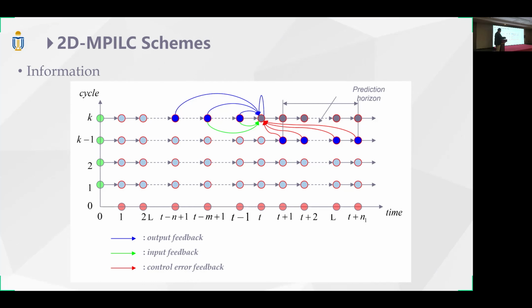One is the traditional time, and the other is batch: one batch, two batch, three batch, the k-th batch, it's repeating itself. So we describe the batch process with two time dimensions, one the traditional time t and the other the batch dimension k, as two-time dimensional dynamics. With this, it's possible for us to use information from the past. And also, the beauty of two-time dimensional systems is that you can use information from past batches to know what's going to happen in the future. With these fundamentals, you can develop a very effective control strategy to control the batch process very well.